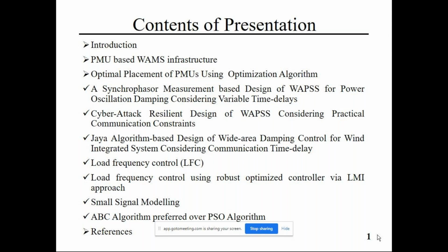Load frequency control, so I am not going into details of the total primary, secondary, and tertiary control and all aspects of that. However, with respect to the intermittency and the stochasticity of the source being connected, robust control is a strong candidate, because you have the exogenous output, you have the disturbance rejection, and you have the robust stability margin.